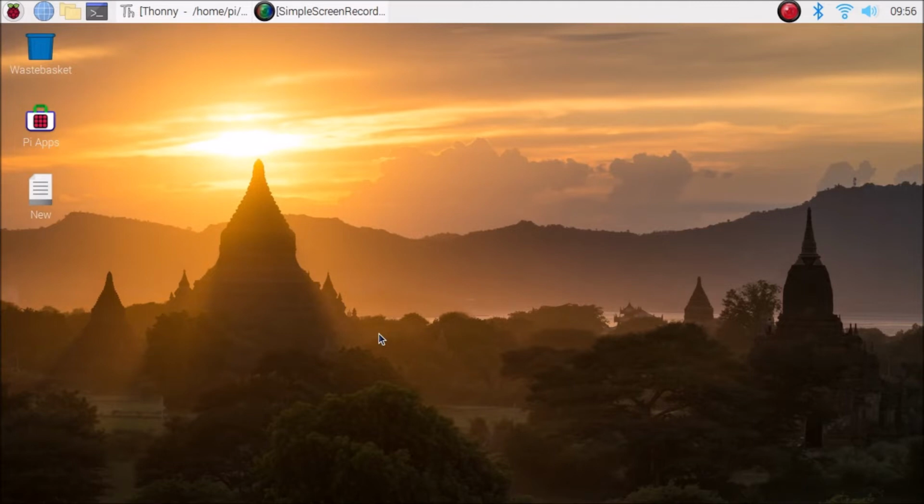As I mentioned, we are going to use OpenCV and CVZone for hand tracking. For that, first you need to install the latest OpenCV, MediaPipe and TensorFlow Lite on the Raspbian Buster legacy version. I will mention the video link. Watch the video and install all these basic modules. Then, how to install CVZone?